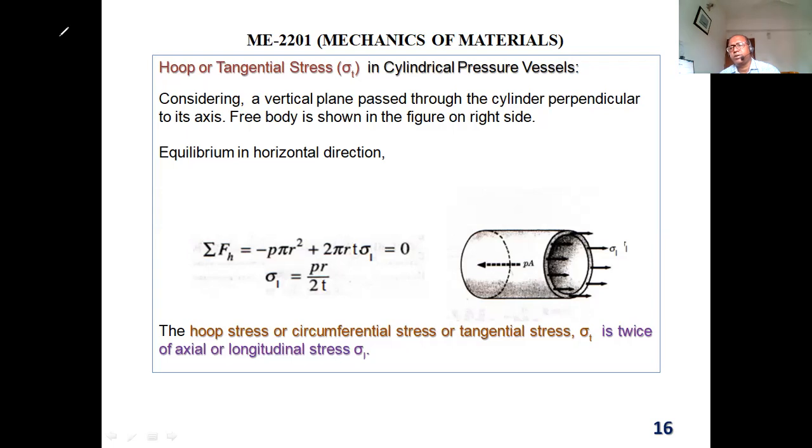Then within 1 week, you burn all the gas by driving your car. Then what happens? The pressure inside decreases. So the cylinder will try to come back to its previous shape. So over the month, one time the cylinder expands, one time it shrinks, maybe 4 times at least. Then over the year, over 5 years, one time expand, one time shrink.